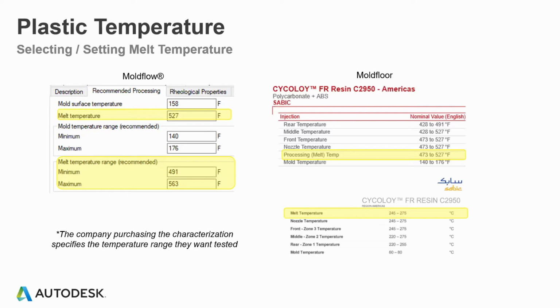It's funny when we ask processors that tend to start in the middle, why do you start in the middle? Well, it's in the middle. And then we ask, well, have you ever reduced the melt temperature to see if you could fill the mold with a lower melt temperature? And usually we get a puzzled look and a smile that they've never done that.